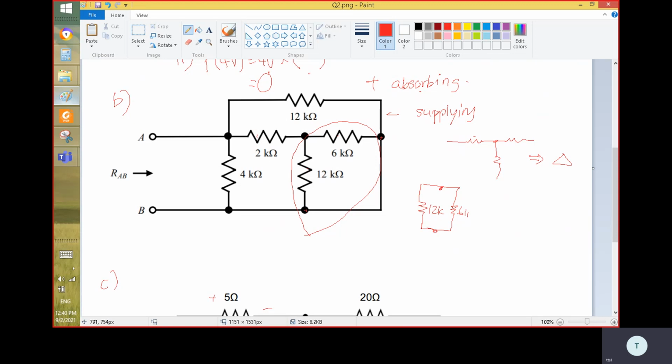After you reduce one component, then this component and this component together, they can reduce some more. And eventually you will reach only one resistor. So this is quite simple, you just need a few steps. Starting from this step here, solving the parallel resistor. Then what you get is this 2k with this resistor you solved just now.